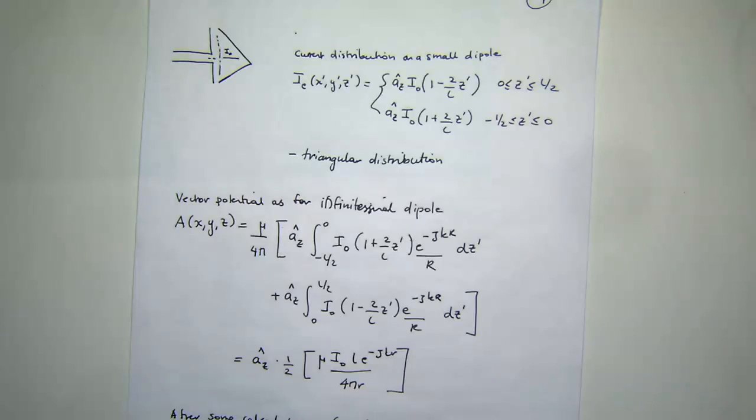If you're trying to include an AM radio station in the form factor of something of this size, you're probably at about a 1,000th of a wavelength, right? And as a consequence, that gave us an indication of how efficient such an antenna is going to be. What we found out was it wasn't going to be particularly efficient, but the advantage that it had was it's small, right? So that was the first thing.